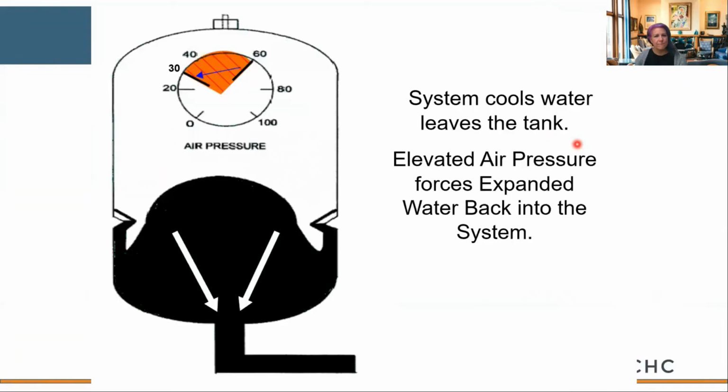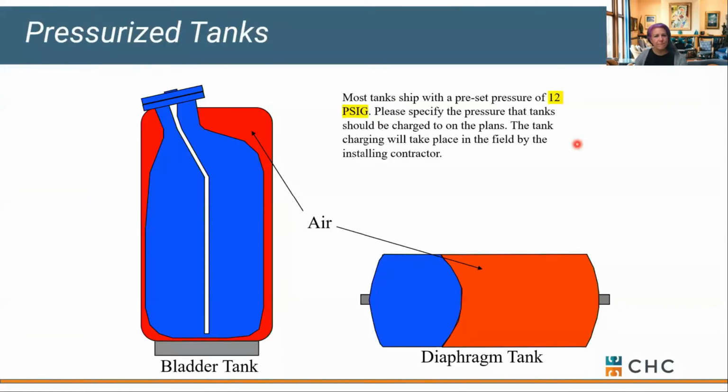Picture a rod poking through your bag or bladder, that's going to cause it to fail pretty quickly. The other thing would be cycling, but again, you're typically talking 50,000 cycles is a good rule of thumb. If you're failing earlier than that, manufacturers can evaluate the thickness of your rubber with some samples from your bag to tell you what's causing that problem. Obviously, chemical attack is another one. Elevated temperatures can also cause some problems.